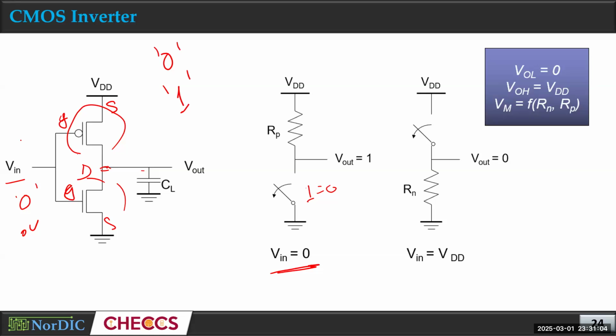And here we have the 0 voltage at the gate, and this is the source, so the source has a high voltage. VDD is actually 5 volt here. If we have 5 volt at the source and 0 voltage at the gate, what's the voltage between the gate and source? Gate has 0 voltage, source has 5 volt. Is it 5 volt or negative 5?